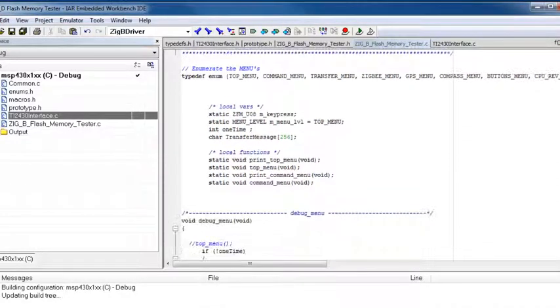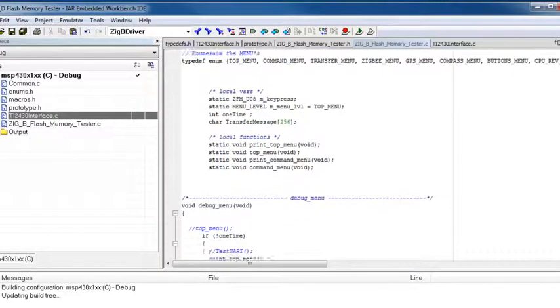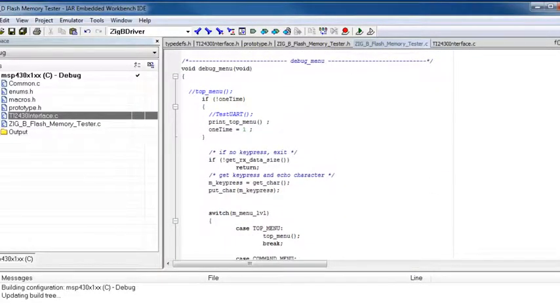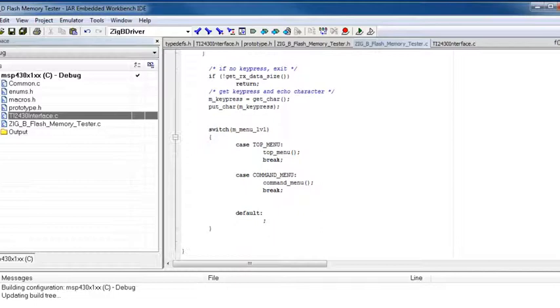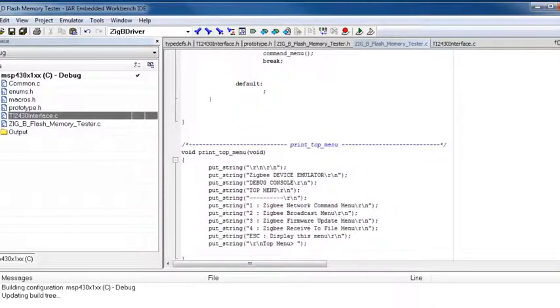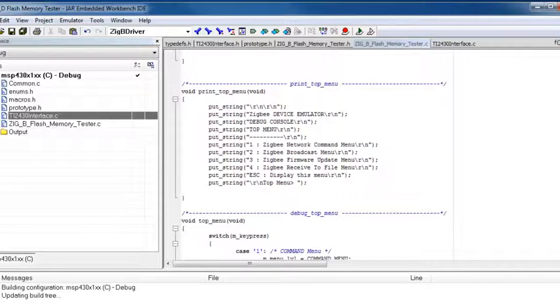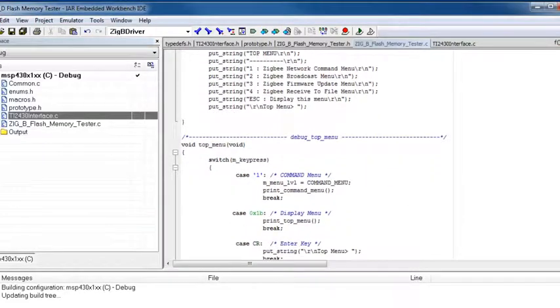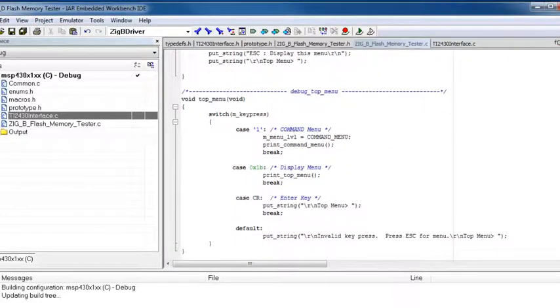So the debug menu uses multiple levels of menus to allow the user to select the appropriate function to execute. These multi-level menus use a top-level function to default to. This top-level menu is displayed the first time through the debug menu function. Below this top level is the rest of the sub-menus. The user can write as many sub-menus as the project needs. Just select a menu by typing the appropriate character into HyperSerialPort.